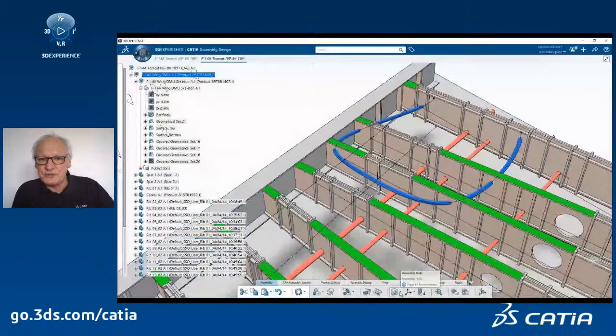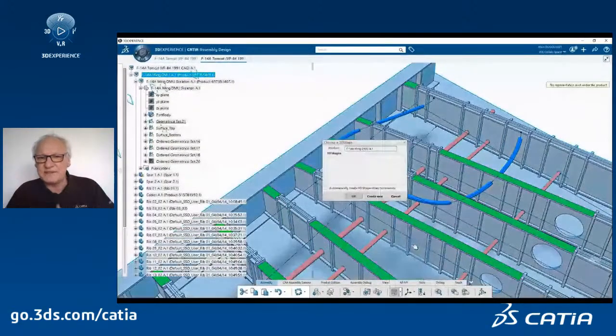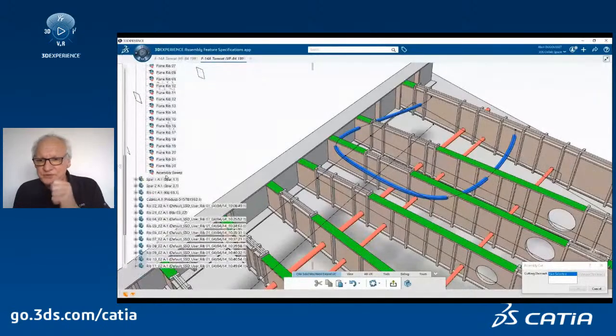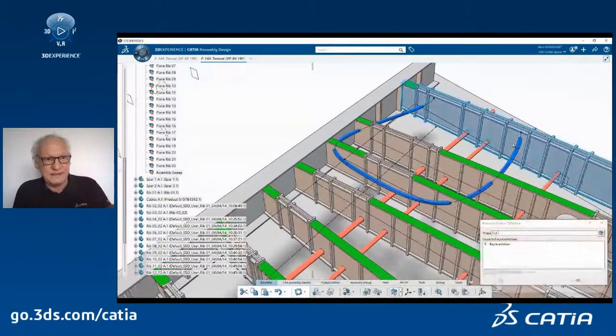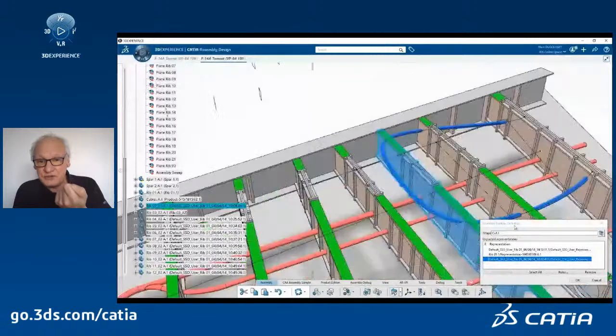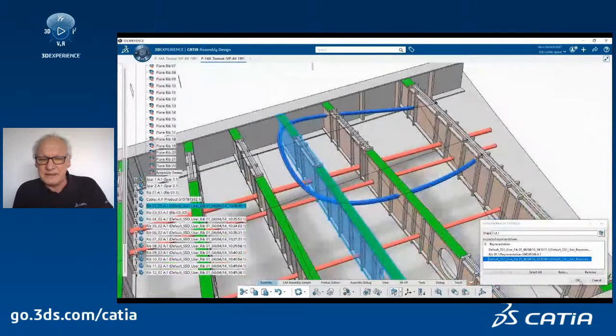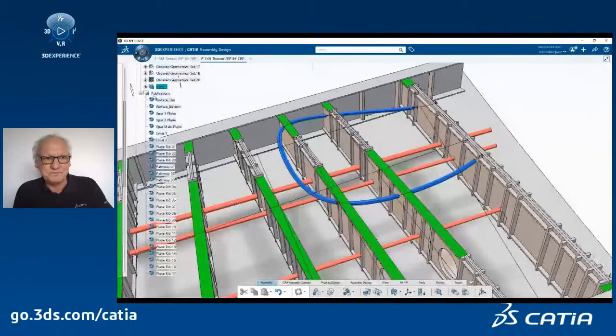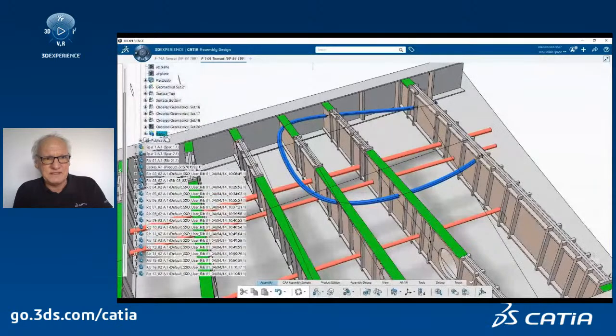And we want to just create a cut, an assembly cut. There are multiple types of assembly features, but here it's an assembly cut. And I will cut my 3 ribs by this blue geometry. So you just select the cutting element, which is the so-called sweep 4. It could have been, and it was, in fact, published as well. And then you select what will be cut by the blue element. Here we go. I just update, and automatically the holes inside the ribs have been performed. You will be able to see them in this body.